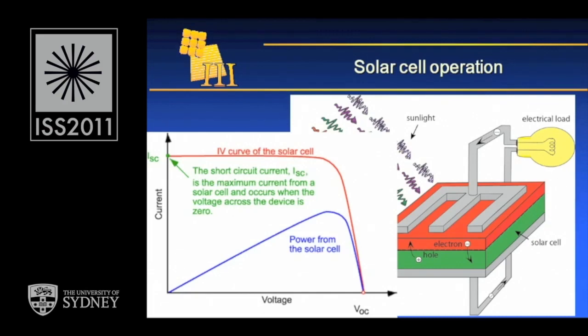The power output is the product of the voltage and the current, so you just get this sort of linear increase in power output, and then around this knee in the curve here you get the peak power output from the cell, and that's the power output that determines the 15% conversion efficiency, the ratio of this electrical power at this peak to the power in the incident sunlight.